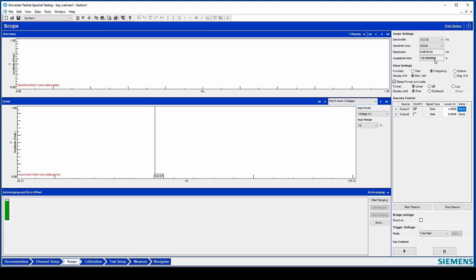You know what he had done, Charles? He had a really, really fine resolution. Yeah, just cranking up the resolution, thinking, hey, this thing will still respond at the same rate. But in some analyzers, other systems, it's true of all digital signal processing or data acquisition systems, that inverse relationship, you may not even see or know that the acquisition time had to be increased greatly in order to accommodate spectral resolution that you required. So you could get potentially strange behavior.